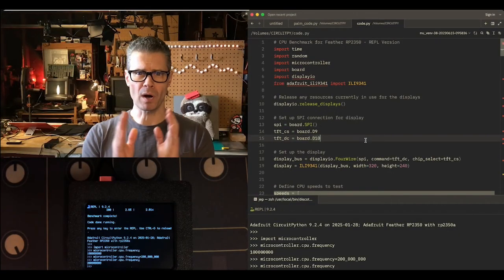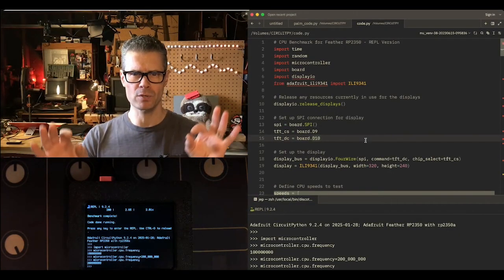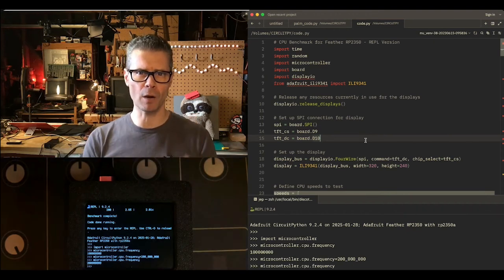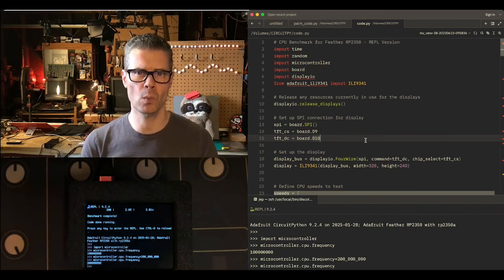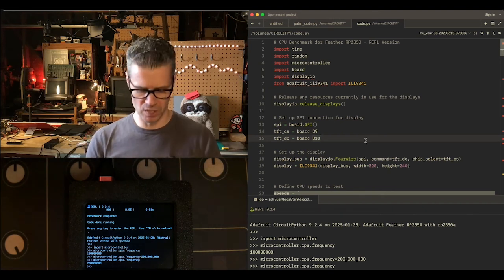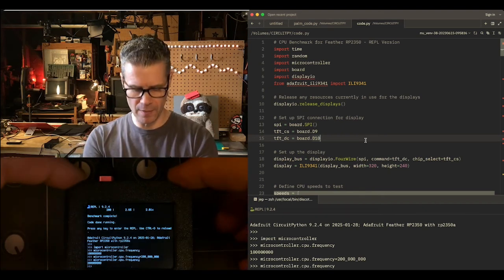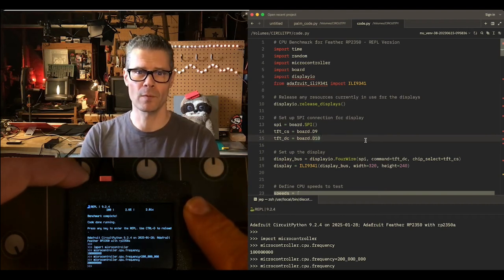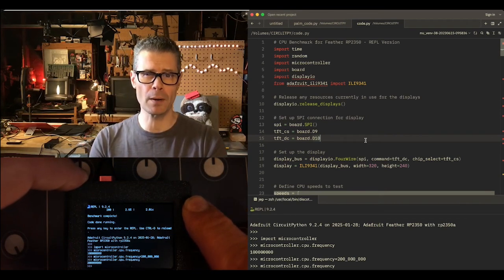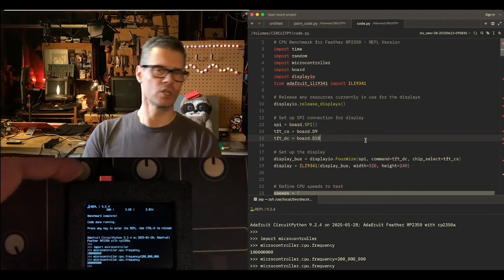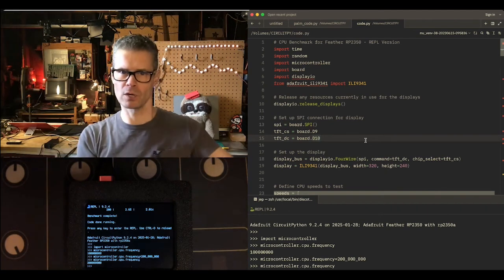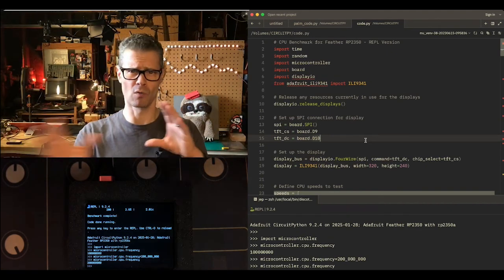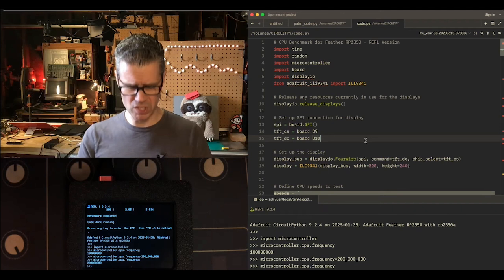For the CircuitPython Parsec today, I wanted to talk about overclocking the CPU frequency of the RP2040 and RP2350 chips. What I have set up here is a Feather RP2350, which now has official support from Raspberry Pi for 200 megahertz overclocking. You can, of course, go wild, go slow to conserve power, or go super fast, but you risk overheating and melting things. But this is definitely a safe one.